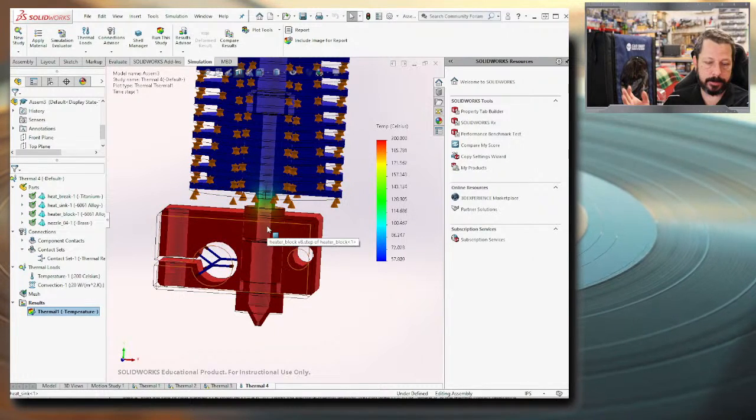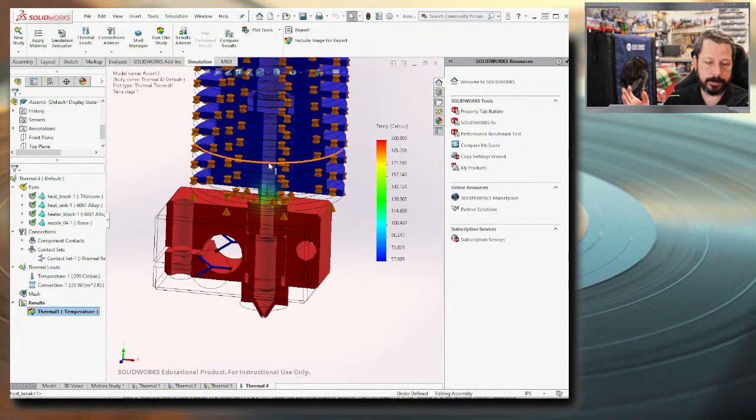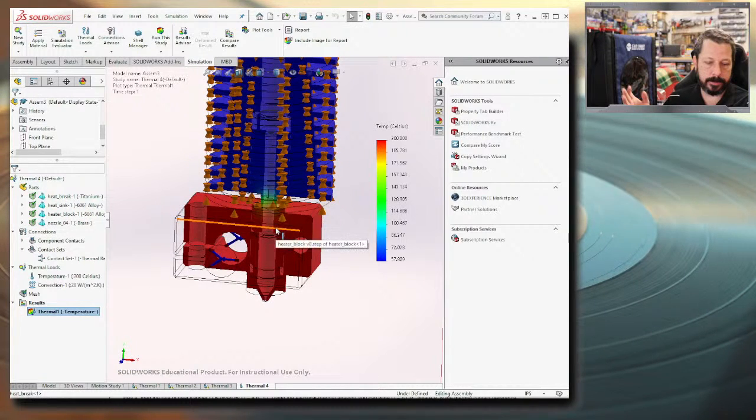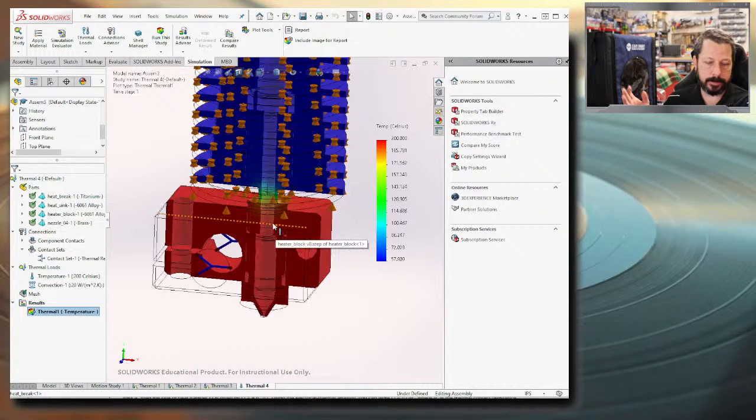The all metal hot end, where you have the all metal heat break, is needed if you want to print nylon for sure. Print a long time with ABS or PETG that need to print at the higher temperatures. PLA is not going to be a problem, and ASA is probably not going to be a problem. PETG is not necessarily a problem, unless for some reason you're having to print it extra hot. But it can print at a lower temperature than what would be the breakdown point of the Bowden tube material.